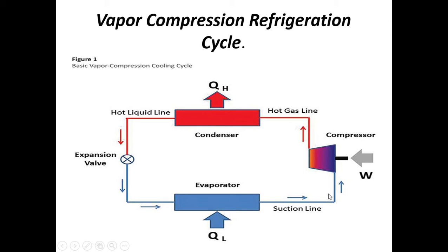When we switch on, the compressor sucks the refrigerant from this region, and the expansion valve prevents entry of refrigerant into this side. So all the refrigerant in the evaporator is sucked by the compressor and compressed to a higher pressure here. A lower pressure is maintained here and a higher pressure here by the compressor and expansion valve together.